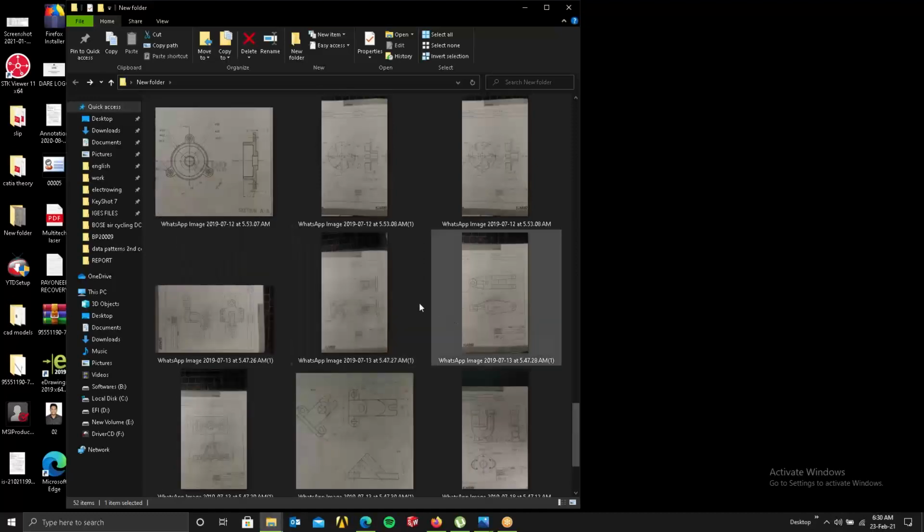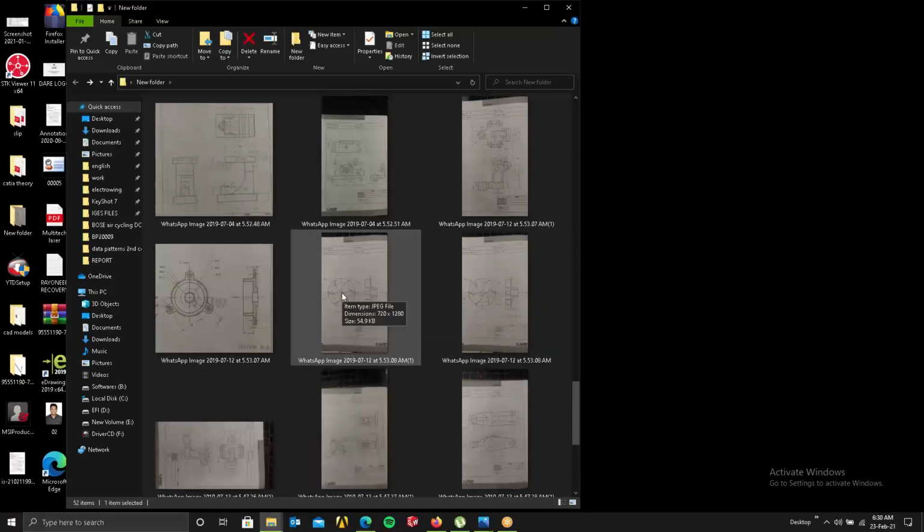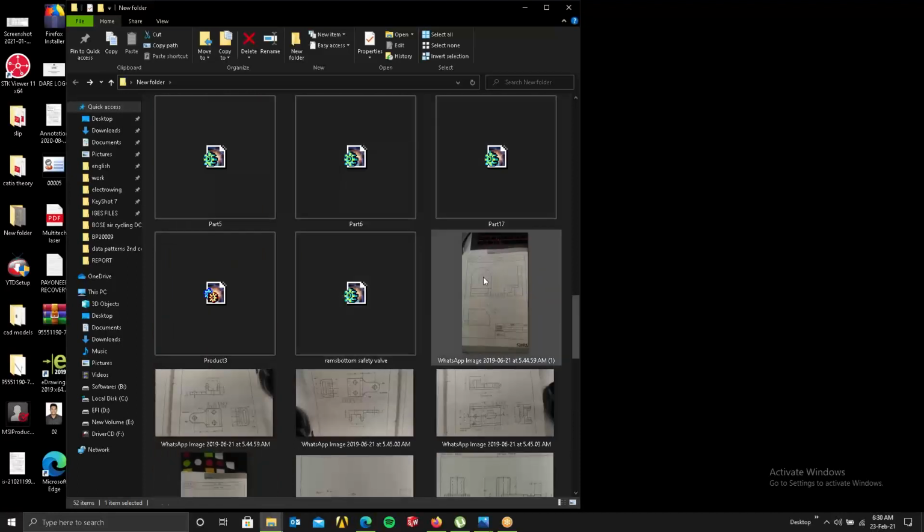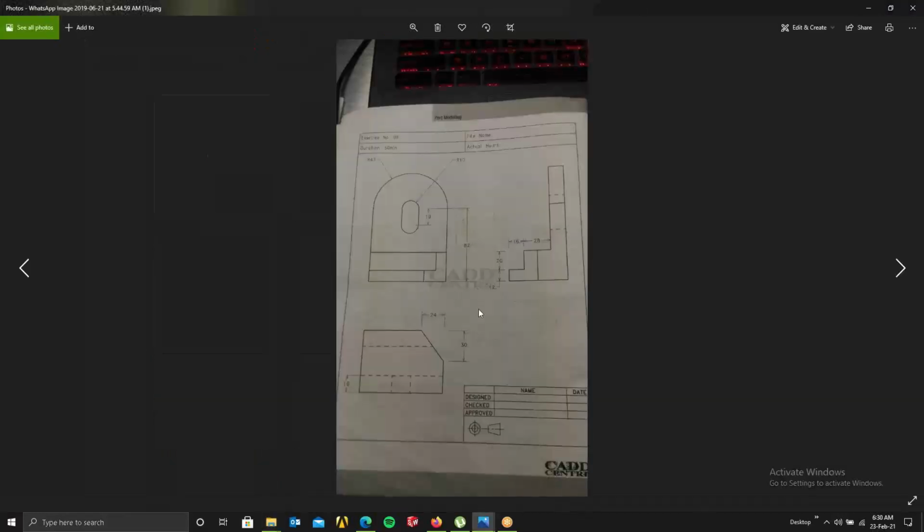A simple example. Let's see. This itself we can do in multiple ways. Now you can see this. If you want, you can start from the top plane, the XY plane, and draw this. Then you can extrude a top face, like this.